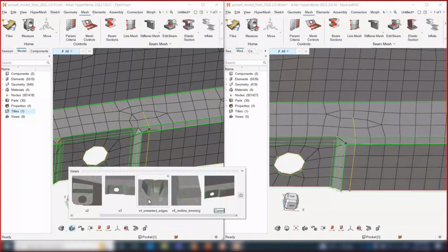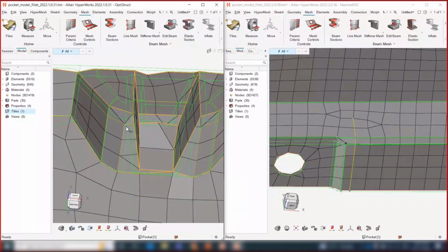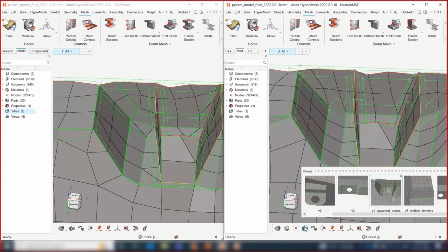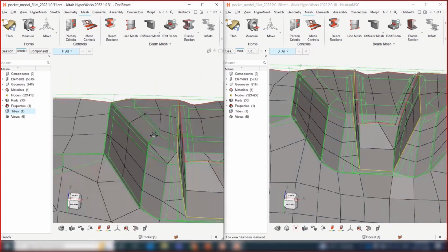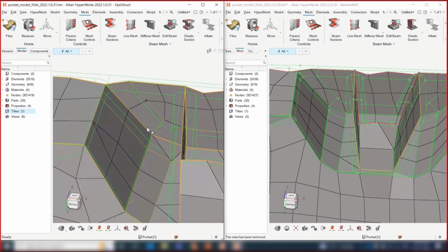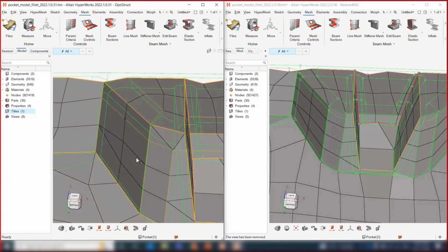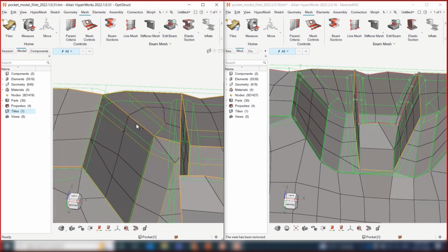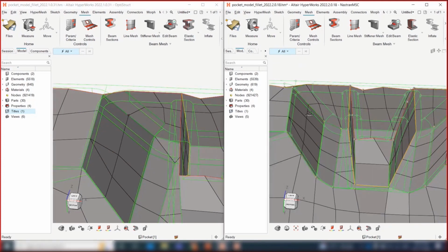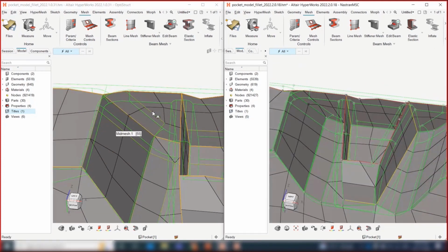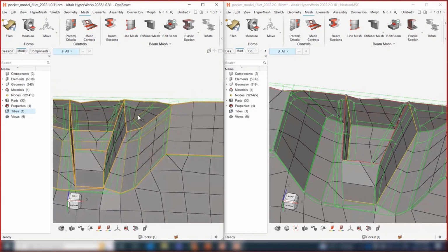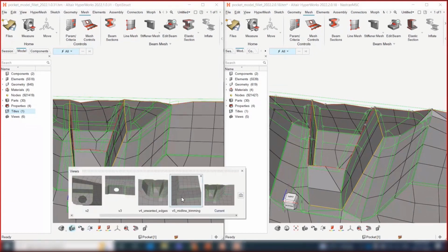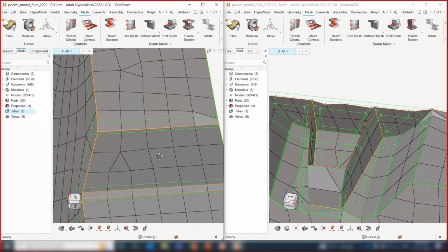So this was also what I spoke about, unwanted edges, correct? What used to happen is these edges on the fillets were getting imprinted. Basically, those didn't have any deviations, but still used to get captured, and sometimes it becomes really manual work to identify them and clean them. So now we don't have any edges getting imprinted at this location. So these kinds of edges are avoided. Now we don't see those edges. So the mid mesh output has a better result now.